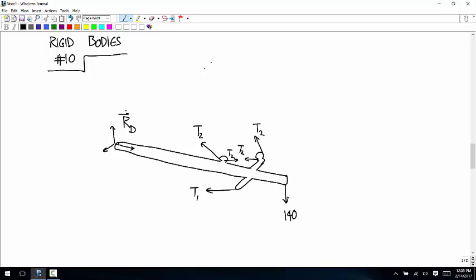And this one has a place that works out just like one of those first examples I did today. This T2 and this T2, they're forces, same magnitude going right towards each other. And if you think of them as having the same line of action, you can see that you can move one of those T2 forces right to where the other one is without changing the problem, because you can move forces along their line of action. And if you do that, you just get two forces acting at the same location, canceling each other out. And you can see that that's not going to do anything.